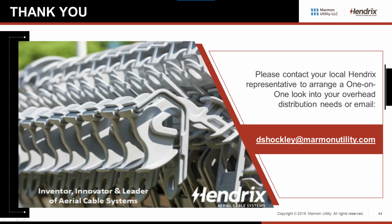And if you work your way through the calculations, it'll actually reduce the impedance of the circuit because the phases are that close together. I scrolled through it relatively quickly, but that's another paper we've got available and we'd be happy to send out. You see about a 20% improvement in voltage drop for the same size conductor, in a spacer cable configuration versus bare wire.